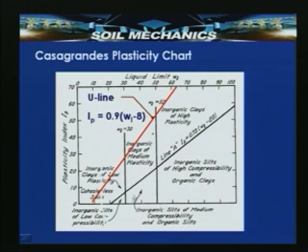So, if you look into it here, some cohesionless soils with low plasticity index lie above the A line, and you see that predominantly this has 6 regions: 1, 2, 3, 4, 5, 6. As you go towards the right, then inorganic silts of high compressibility and organic clays are below the A line. Inorganic clays of high plasticity are above the A line.